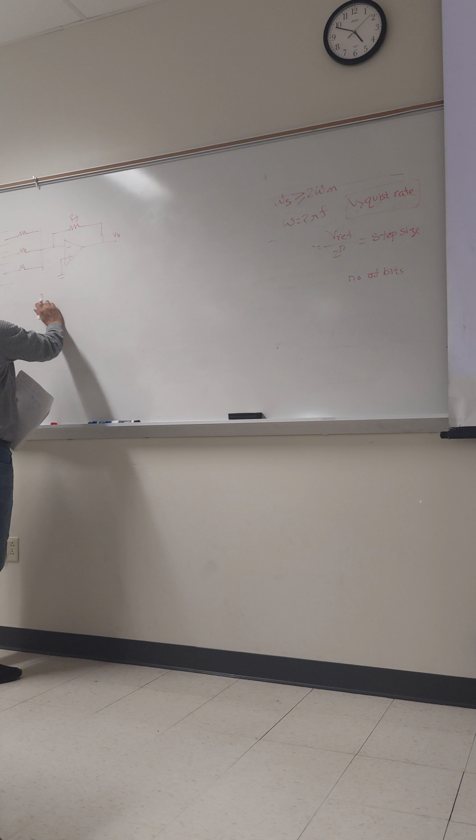Okay. So what is the V out equation? As we have the inverting amplifier, it's a negative sign, so V out is equal to minus IF times RF, or we can say minus RF times V reference into V2 by R plus V1 by twice R plus V0 by 4R.